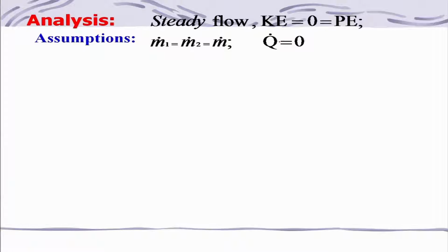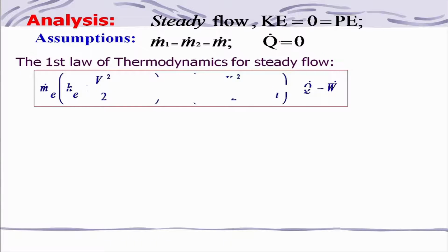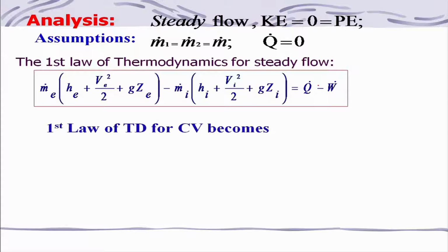dissipated during either the compression work or the expansion work, in a compressor and turbine respectively. So, the first law of thermodynamics for a steady flow process, we have already seen this expression, right. So, we can apply that. We are basically saying this change in kinetic energy is 0, potential energy is 0, and this is 0 because of adiabatic in nature, right.